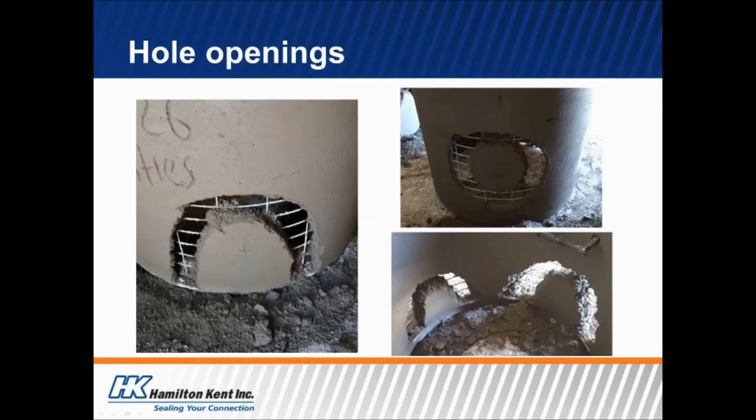But then there is also some risk of affecting the structural integrity of the structure if the concrete is too green. So if they start poking that out and that concrete starts to shift or fall, then that's going to cause a big problem. However, when shipping it, it helps to maintain the structure's strength overall because it has that reinforcement consistently running through it. And it makes it very easy for the contractor at the job site to basically just cut that wire out and create the opening. But this is obviously not going to be a very clean hole. It's not going to be very smooth or consistent, so definitely not intended for a rubber connection.